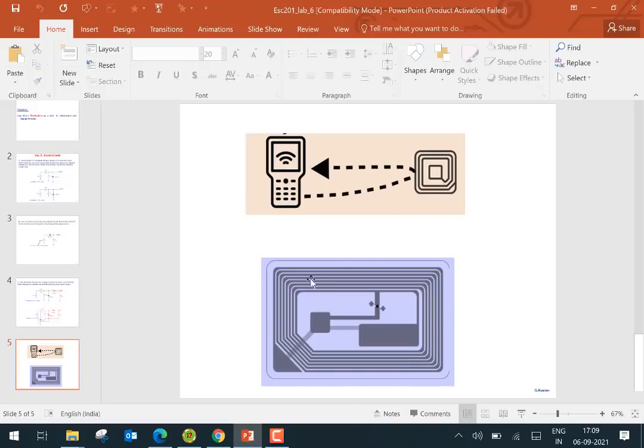Now this shows a tag in more detail. There is basically an LC tag circuit here, whose goal is to generate the RF signal, and there is an IC here. The entire circuit is powered by the signal which is captured by the antenna. When you capture the signal, the sinusoidal voltage which is generated is often not of sufficient amplitude. So, for example, let's say the amplitude is 1 volt, and my IC requires 3 volts to work here. Then that 1 volt has to be tripled. So we need a tripler circuit to increase the amplitude to 3 volt, and those 3 volt can then power the IC. Once the IC operates, it can generate a signal which is sent back to the reader. The identification information can be sent back to the reader.